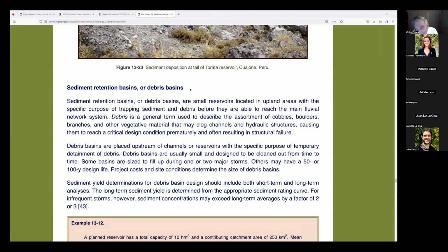Remember, in sediment calculation, you can afford to miss it by 50%, which is depending on how you look at it, it could be 100%, 50% on one side, 100% on the other. So they missed it by 50 to 100%, and it was fine. And on the side of safety, the debris basins did not fill up. They actually filled up to the middle, which was good.